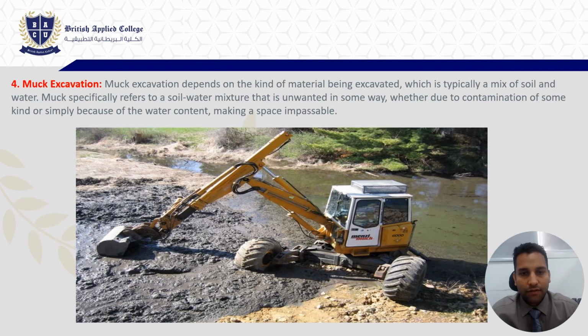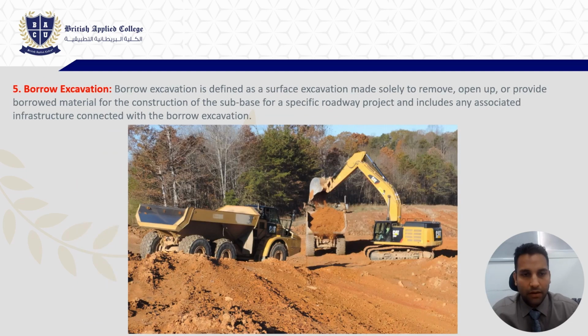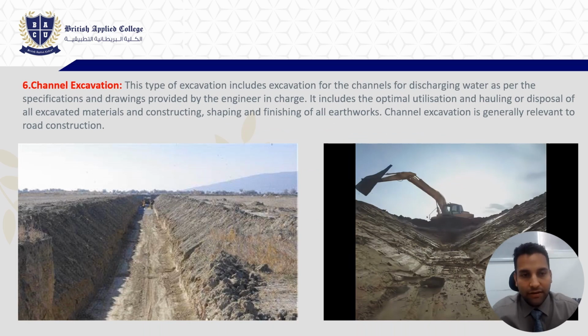Muck excavation, if you have a muck area wherein there is a lot of slurry and a lot of loose soil, that is supposed to be removed. This is known as your muck excavation. Similarly, borrow excavation, we borrow soil from another place to place at our site. That is known as your borrow excavation. Channel excavation, when you create an excavation for passing water from one place to another, is known as your channel excavation.